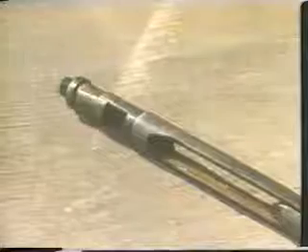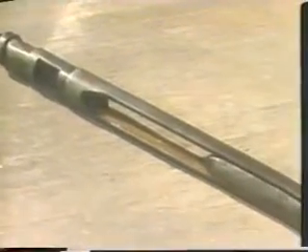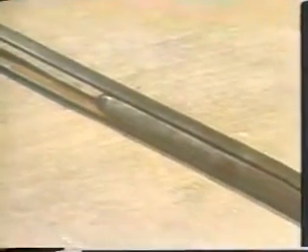The jars allow the wireline specialist to deliver the hammering blows that are essential to perform most wireline operations. The jars are attached to the tool string below the stem. They look like two long chain links which can be slid together or apart. The distance that the two lengths can move from one extreme to the other is called the stroke of the jars. In practice, jarring can be done either up or down.